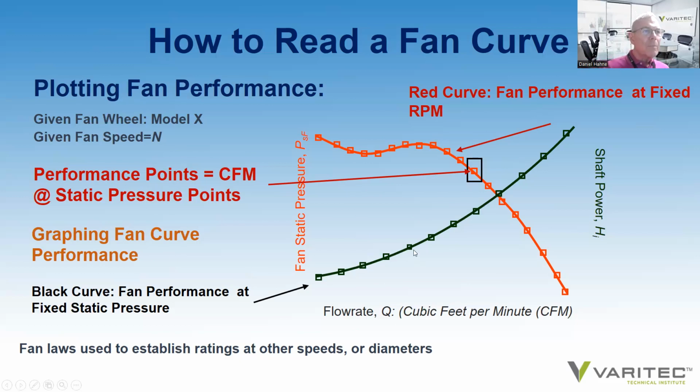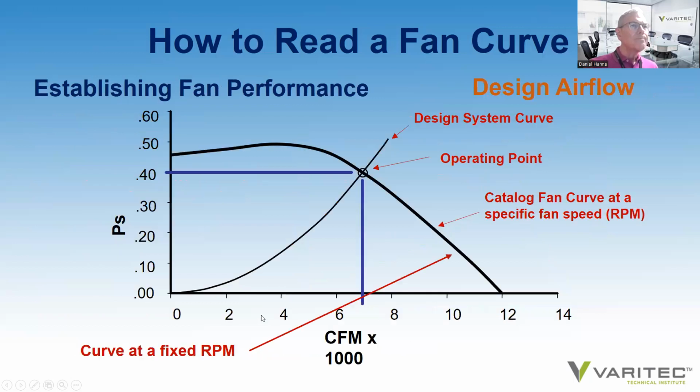The curve in black is actually changing the fan RPM. It's called the system fan curve, and changing the fan RPM while maintaining a constant static pressure and reading the airflow rates in that manner.